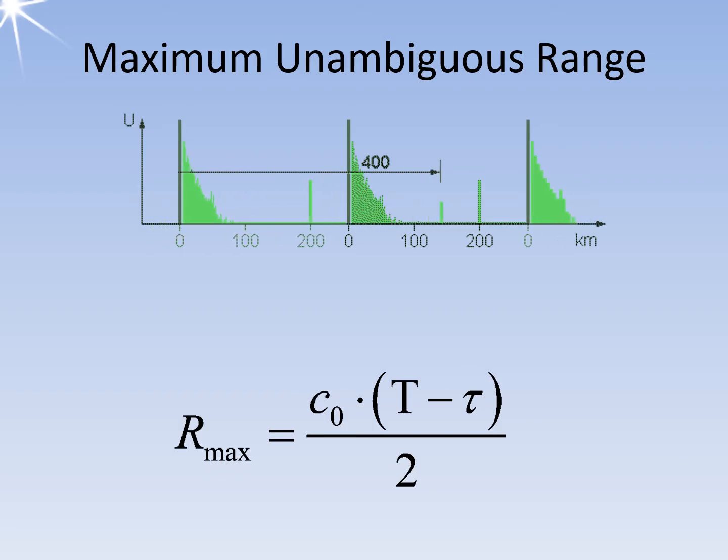Now, the position of the ambiguous echo signal in the following pulse period is no longer stable. Instead of a small bright arc on the screen, a cloud of dots appears, and the operator can see that this cloud cannot be a target. A modern radar signal processor can properly combine these dots and then display the target at a proper distance. This process is called unfolding.